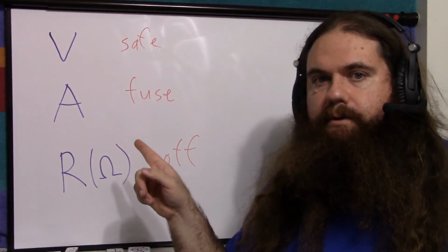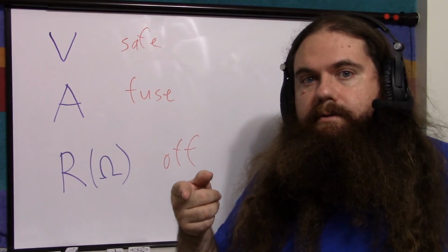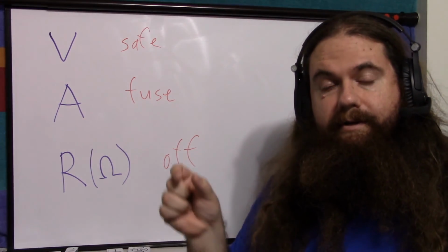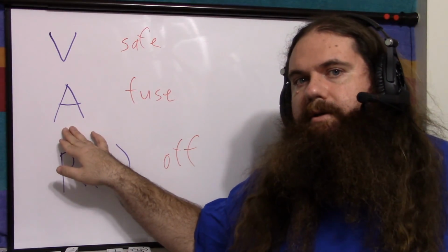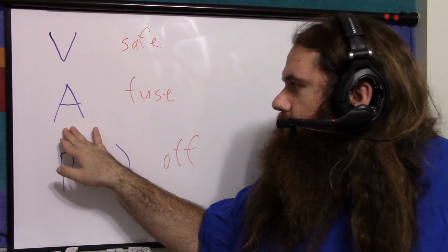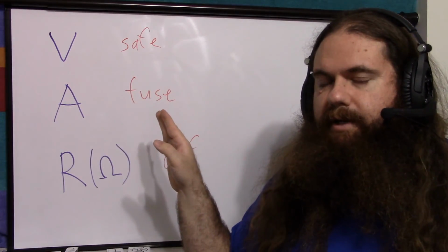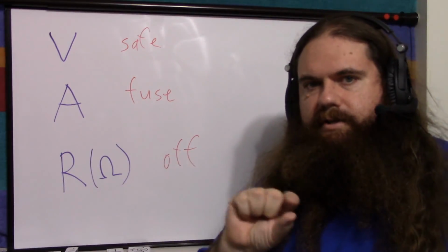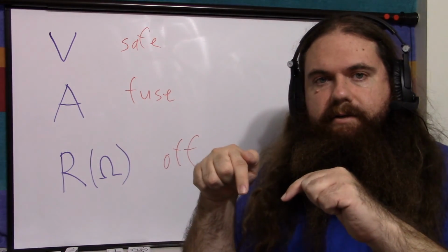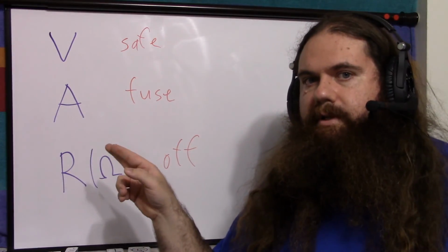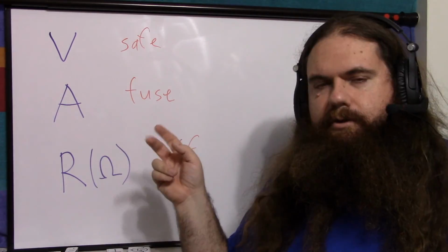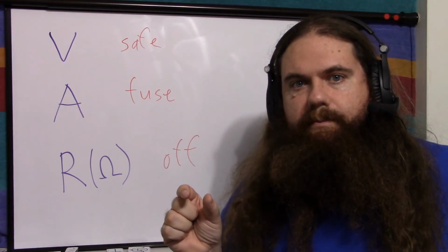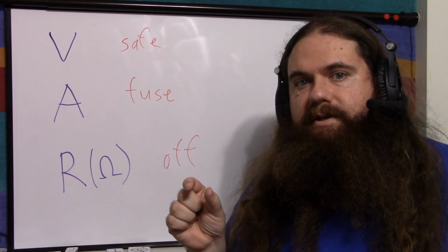is limited by a fuse, and I actually blew a fuse on my multimeter just measuring a 9-volt battery. The amp meter is another passive sensor, but this one has very little impedance, almost none. Basically, it just measures the current going through it. You stick it in series with the circuit. So you again do it with a live circuit, but make sure that you know what you're measuring before you measure it. Don't just try to measure how many amps a battery can put out, because the answer is enough.